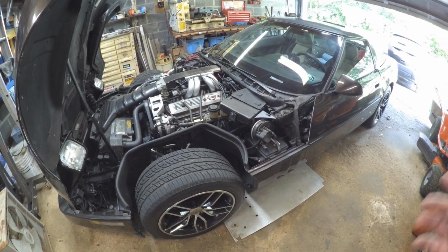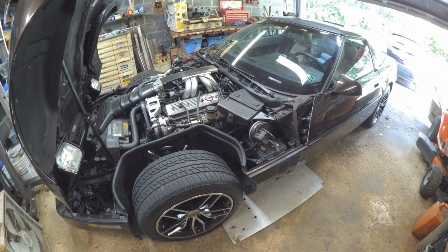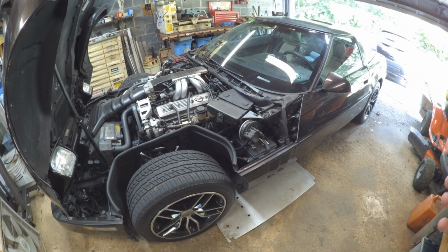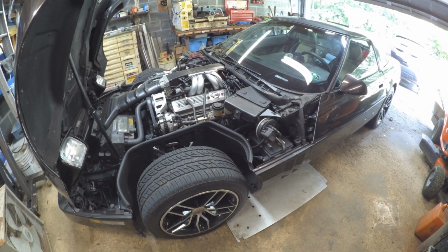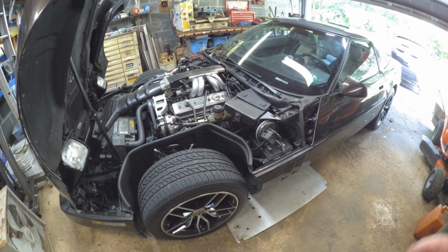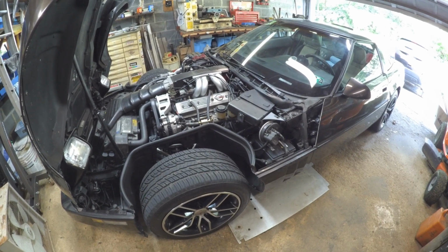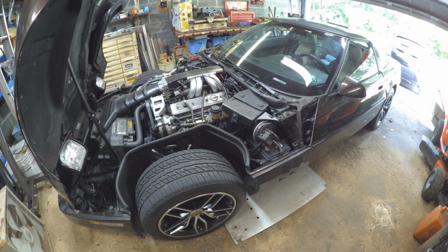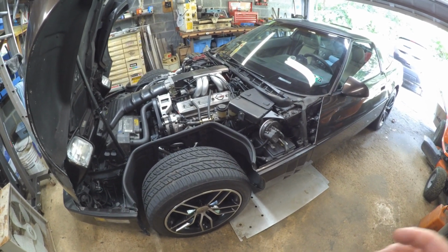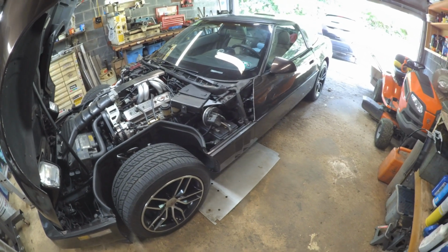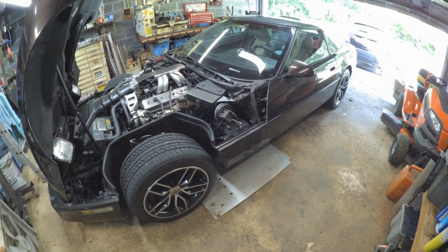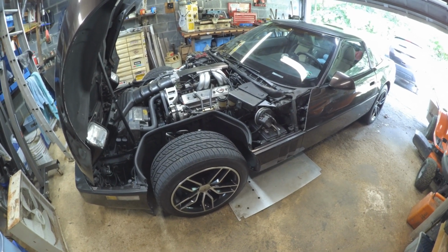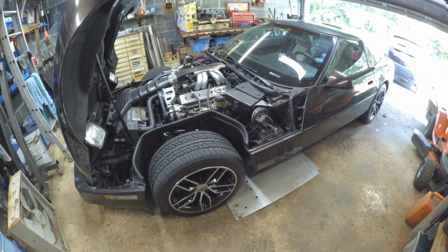I only noticed because I was on a long trip to a car show, like 2 hours from here, and the wideband was reading real lean, and then at lower speeds real rich. Even though it was lean and rich, it wasn't enough to affect drivability. So if I didn't just happen to glance down at the wideband, I would have never known there was a problem. So I'll go inside, open up Tuner Pro, and do a screen recording of that, I hope, and show you what happened.